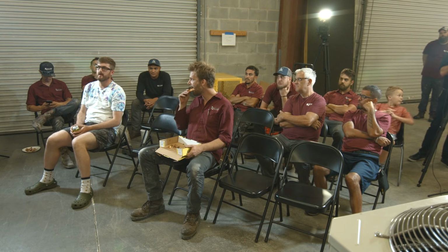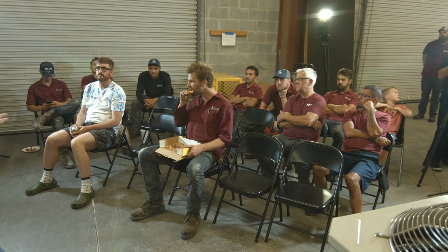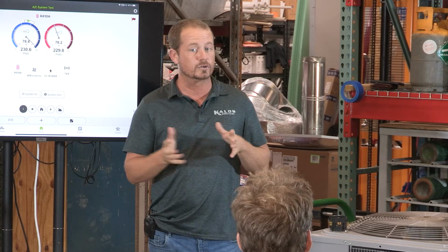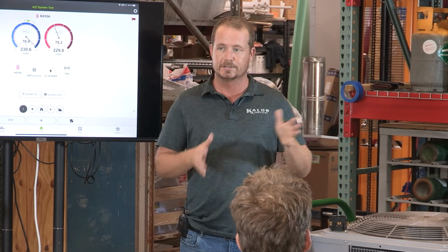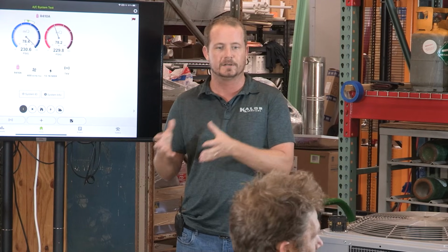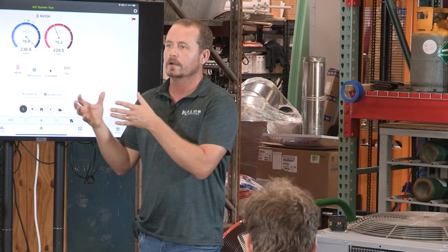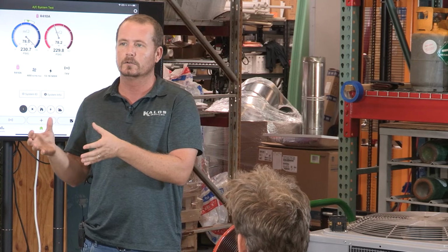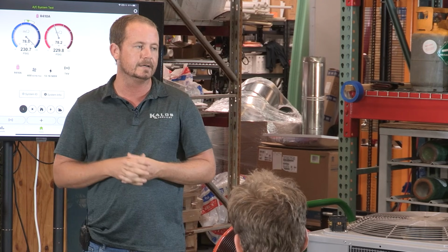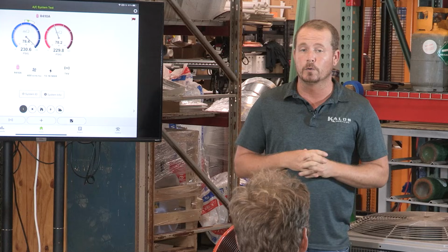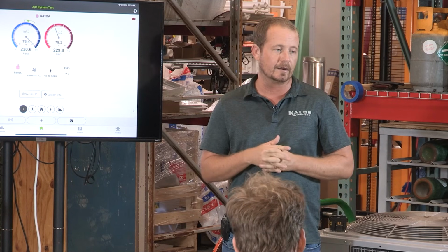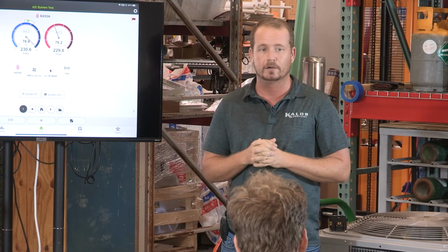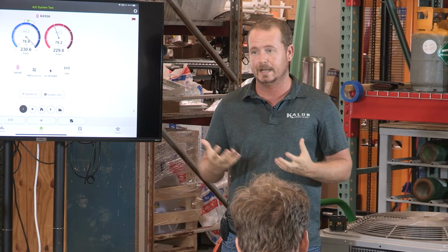Because we're just trying to maintain the airflow it's programmed to be at. It's attempting to maintain airflow or torque, depending on the motor type. X13 motors, which is a brand name, constant torque motors, are going to attempt to maintain torque. ECM or true variable are going to try to maintain airflow. So that's what you watch for. When you hear an air handler that's howling or a furnace that's howling, always stop and look at static pressure.